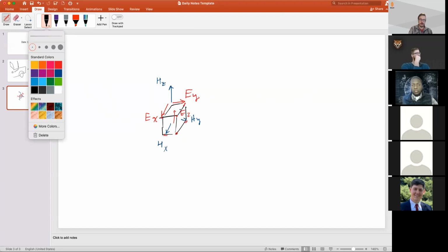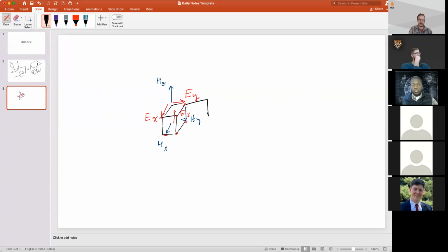And then you could go on, right, and there'd be another block adjacent to this that does the same thing, until at some point, right, your antenna is broken up into these small blocks where you're solving for the fields at each point. And so the smaller you make those points, you can solve for all the fields. So that's how computational electromagnetics worked.